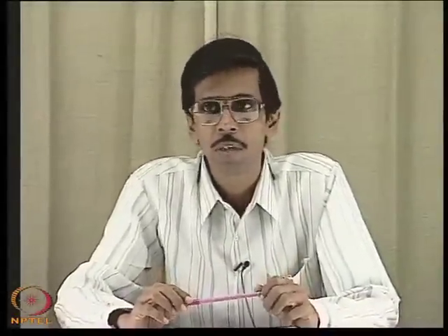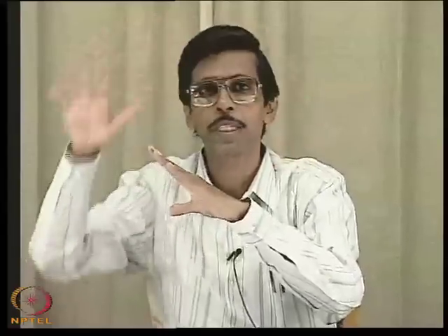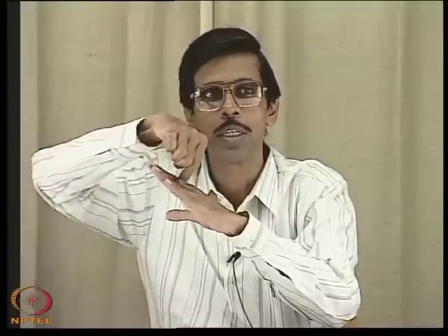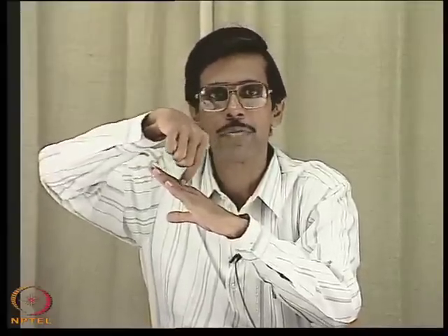Good afternoon. I welcome you all to this session of fluid mechanics. Last class we were discussing the hydrostatic force exerted on a plane surface submerged in a static expanse of fluid. And what we have finally concluded is that if there is a free surface of fluid and a plane inclined surface is submerged in this expanse of fluid, then the pressure force is exerted perpendicular to the plane surface at each and every point.